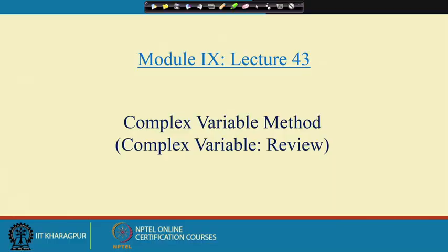Everyone, we are going to start today the 9th week of this course, and the topic that we'll cover this week is the complex variable method. We have derived the governing equations, and over the last 3 weeks we have seen how those equations can be solved for different problems in elasticity. The methods that we used were mostly the power series method, either in Cartesian or polar coordinate systems.